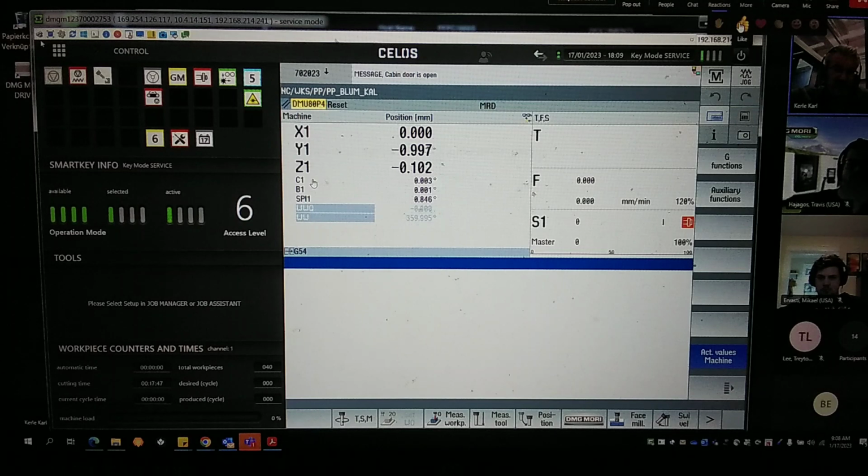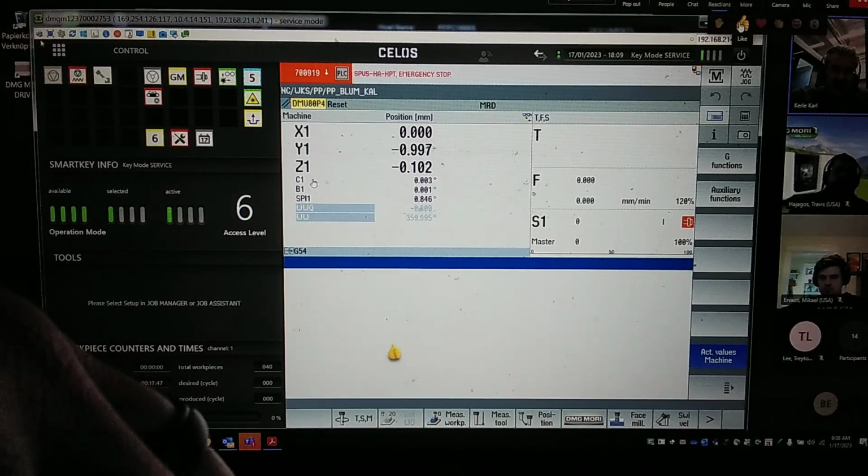So that means we have 8 auxiliary axes for controlling the position of these discs. Then we have a tool changer and a cross axis minimum. So that means we have 10 axes only for the tool management. That's why we need the channels. Okay, so far so good for everybody.